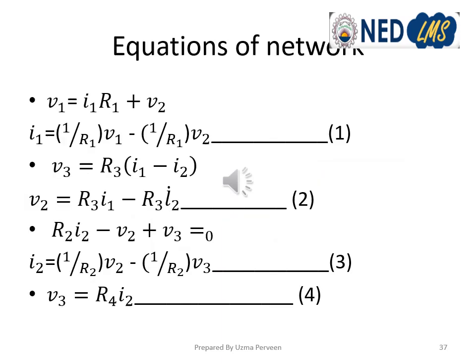Next, we have written here the equations for this circuit. It is quite obvious that we have decided the number of variables or the number of nodes: V1, I1, V2, I2 and V3. So in this network, the 4 possible output nodes are V3, I2, V2 and I1. So it means that we'll need 4 equations. So we have made 4 equations here. For the first, I1 equals 1 upon R1 V1 minus 1 upon R1 V2. It is quite simple to write, simply applying KCL and KVL to the network. Then we have an equation for V2, and then we have equations for I2 and V3 respectively.